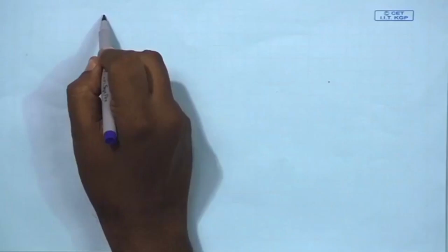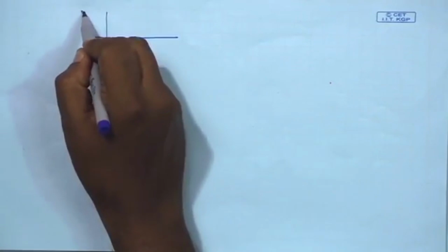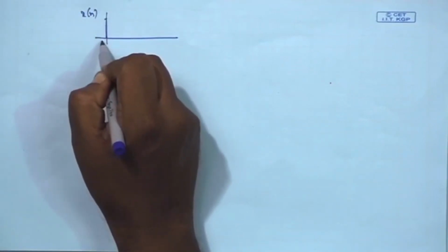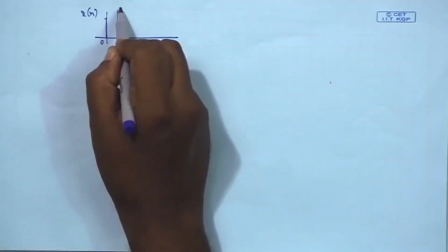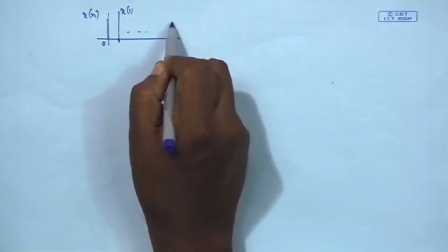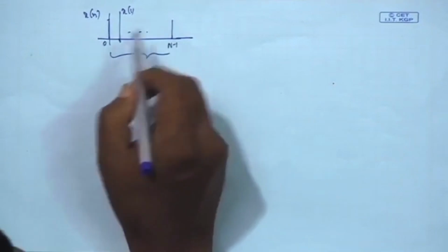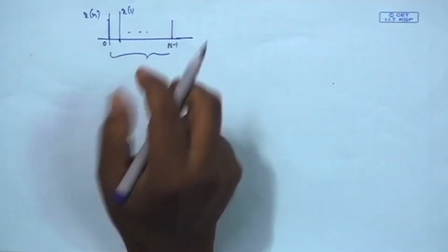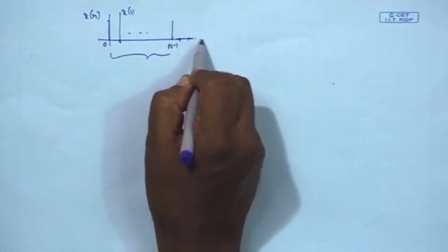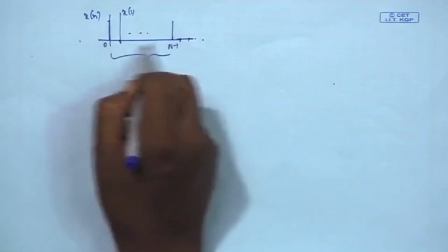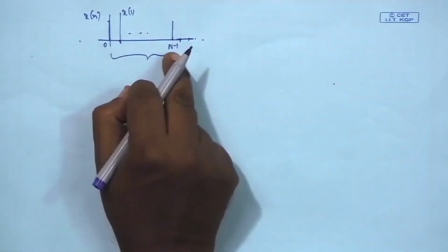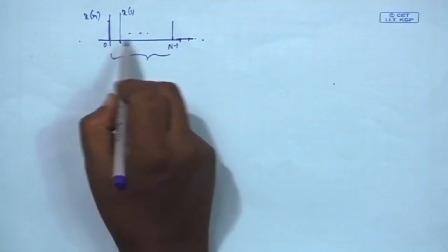Okay. So, yesterday we started with DFT. If the sequence is finite, x[n], x[0], x[1], ... up to, say, N minus 1, this is the duration over which the sequence is given. So, it is a finite length sequence, outside it is 0. Sometimes this range is called a support. So, support is finite, from 0 to capital N minus 1, over this it is defined.